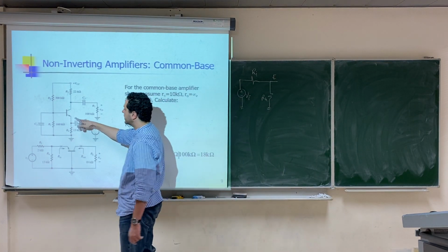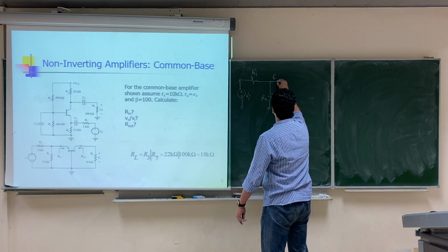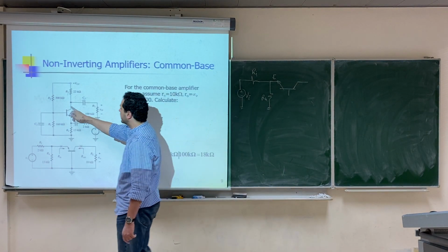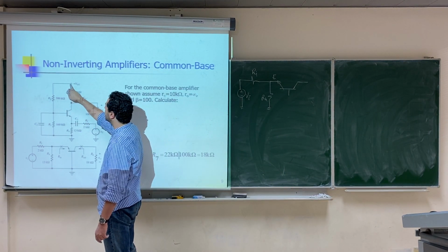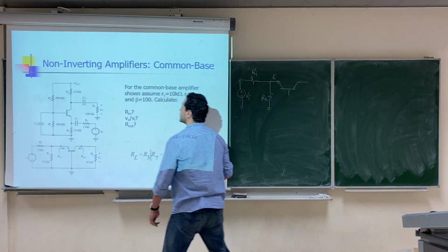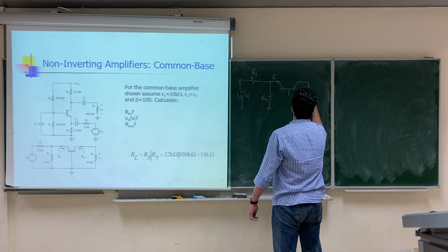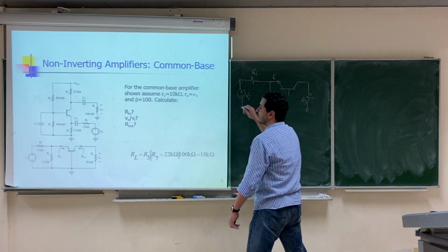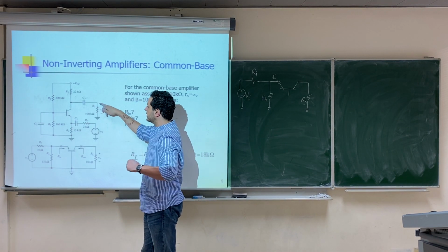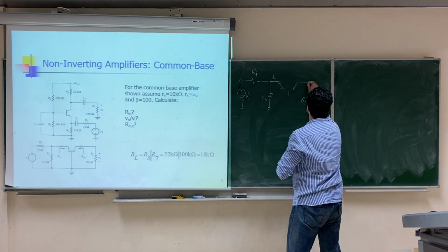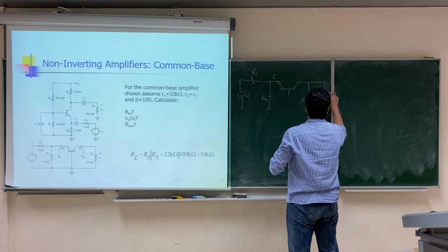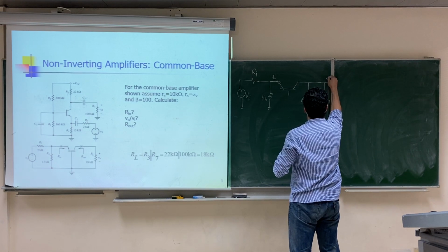Then let's put the transistor as we have here. This is the emitter, base, collector. The collector will be connected by resistance R3 towards ground again, because the DC supply will be deactivated, will be grounded. So the collector will be connected towards the ground by R3, and then the collector also has another branch, a short circuit, and then a resistance R7 towards the ground, and this is where we take our output from.